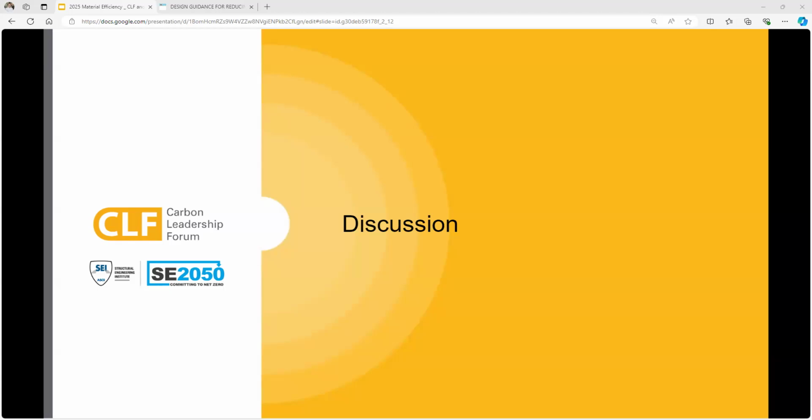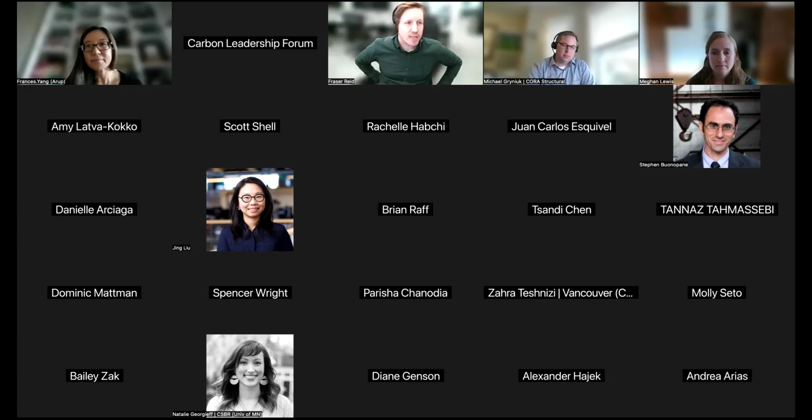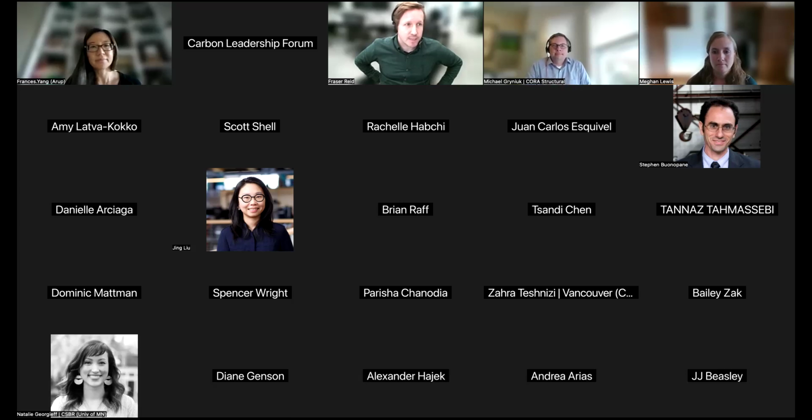I was just going to add, back to the time dependency on carbon and making the big decisions early. I think one barrier I see is wanting to get too detailed in your embodied carbon measurement early on in a project, when really what you should be doing is order of magnitude comparisons and trying to influence those big decisions early. So, does the building need a basement?